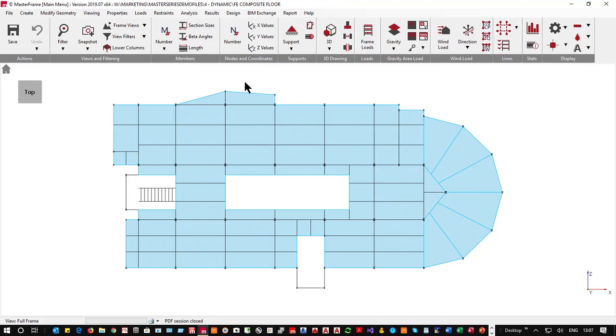Because our vibration analysis is at quite low stresses on the structure, and we're talking about footfall analysis, people walking past a corridor causing an effect, or people finding when they're walking or dancing that it's too springy. This is not loading the structure up that much. So the document also recommends that you do a fixed rigid analysis, because the concrete is rigid at those levels.